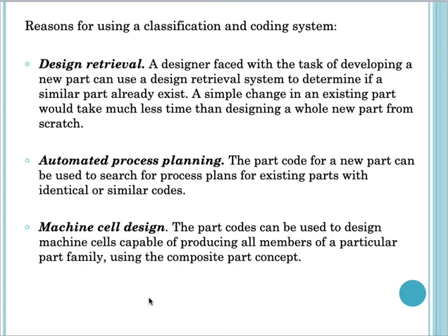The length and diameter ratio is also important here, along with material type, part function, major dimensions, minor dimensions, tolerances, surface finish, major process, minor operations, machine tool, operation sequence, production time, batch size, annual production, fixtures needed, and cutting tools. Those are the attributes we have seen for part classification.